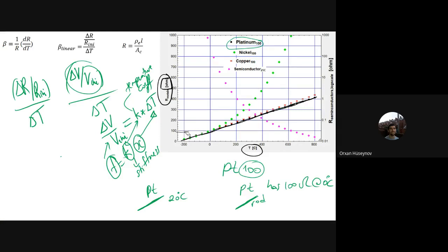It should be at 25. At 25 degrees Celsius, it has 100 ohms. So that is the reason that I have the error here. It is 25 degrees Celsius.